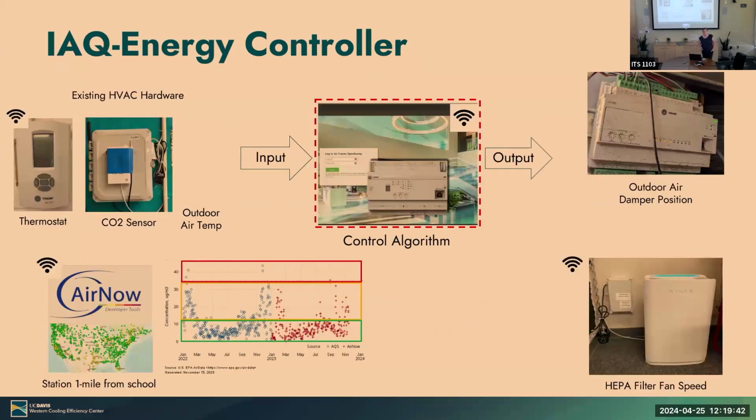Theresa? Yeah. Can I ask you a question? In my experience in real commercial buildings, there are 3 dampers that control that: outdoor air, the exhaust damper, and the mixed air damper. And on a lot of HVAC rooftop units I've seen, there are not 3 dampers. There's maybe only 1 or 2 to try to vary the fraction of outdoor air. On those Trane units, how many dampers were there?